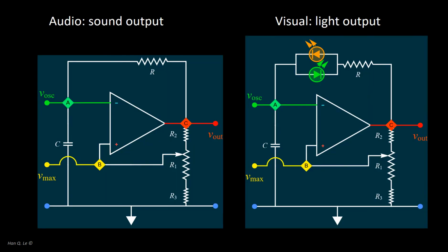The study in previous step A1 on the capacitor charge and discharge behavior was conducted manually. The circuit to be built in this step A2 is a further study of the charging, discharging, and even reverse charging, that is, charging to an opposite polarity behavior, and all done automatically by the circuit itself, without any need for external input control. The circuit can also be considered as a further study of the OpAmp property, in which the ultra-high gain in open-loop configuration causes saturation and instability.